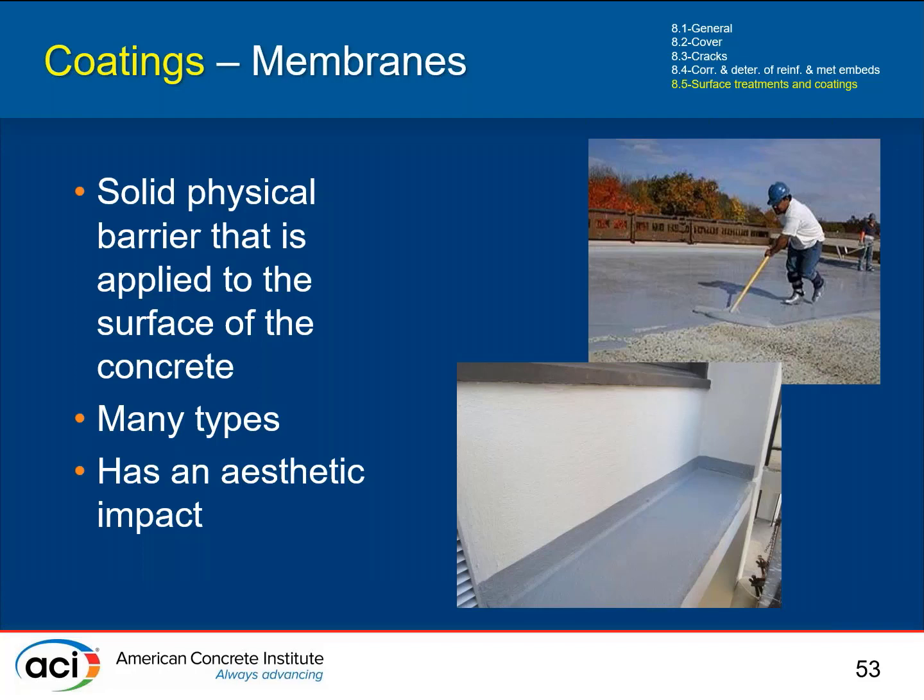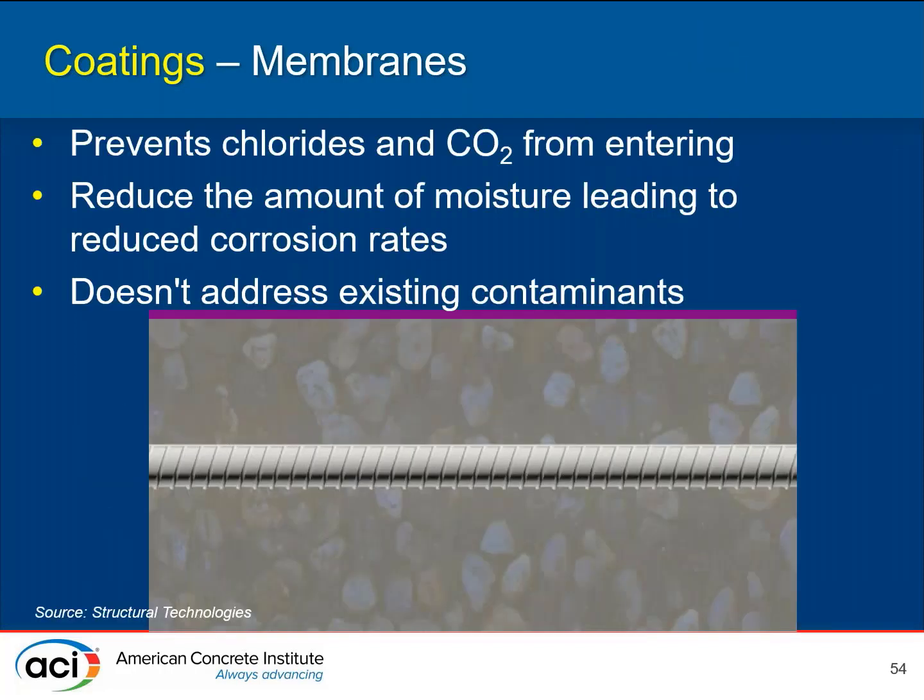And because it's something that's applied to the surface, one of the aspects of it is that it does have an aesthetic impact. So you need to consider that, and make sure that the owner is expecting it, that all of a sudden you have a gray rubber surface instead of your nice shiny new concrete. As you know, you need to prepare them for that.